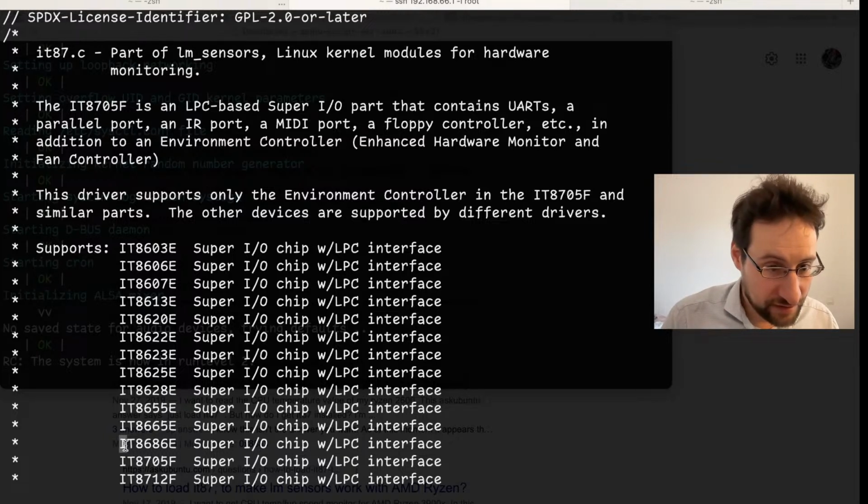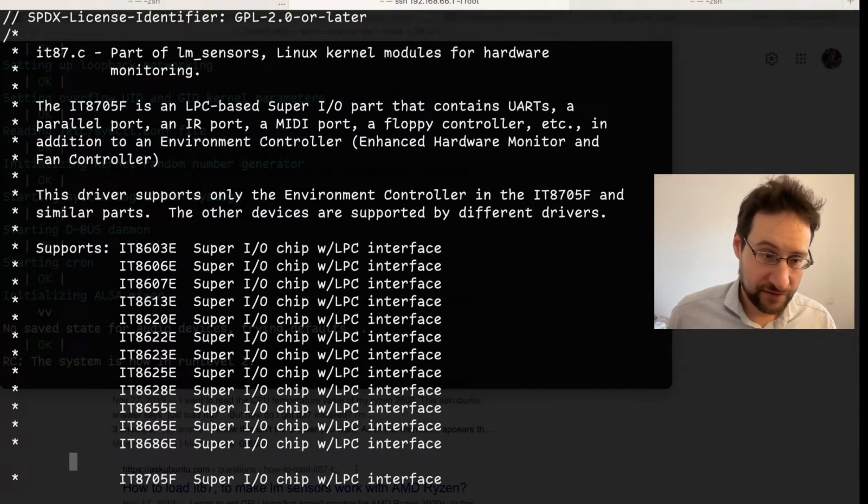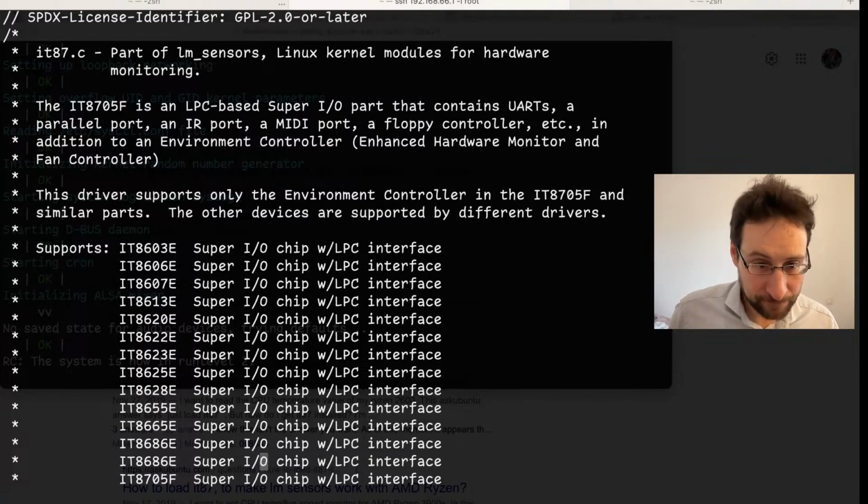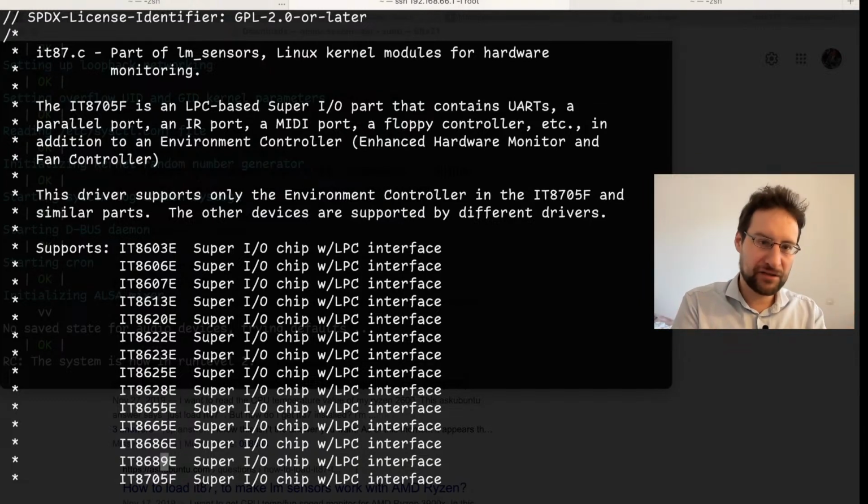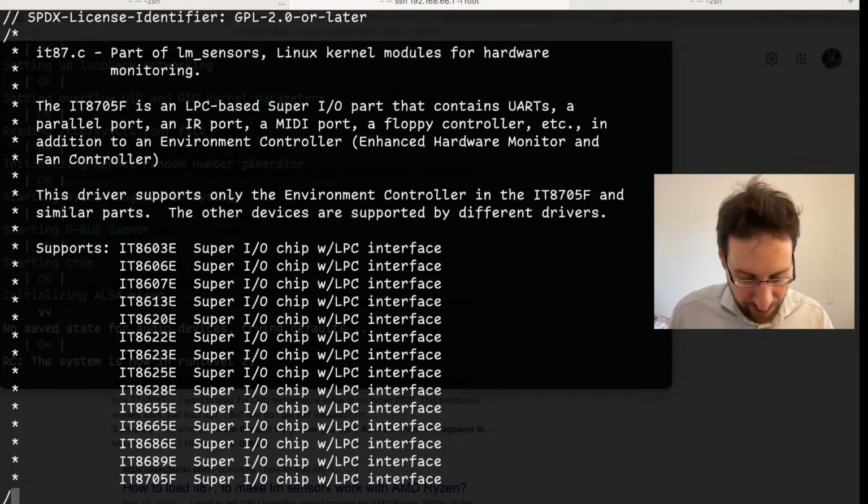86, here. If we want to do it nicely, we just copy. Do they have tabs? No, they don't. So we have 89. And there should be a bloody standard, right? The Super IO chips are also similar. Maybe they removed floppy support, because sure, there are probably some differences. But I don't care whether this Super IO chip still has 80s floppy support or keyboard. All I want is my sensors. For sure there are differences, like certainly some legacy support removed, but we are speaking about ADC controllers for temperature sensing, right? And as you see here in this file, they are pretty similar.